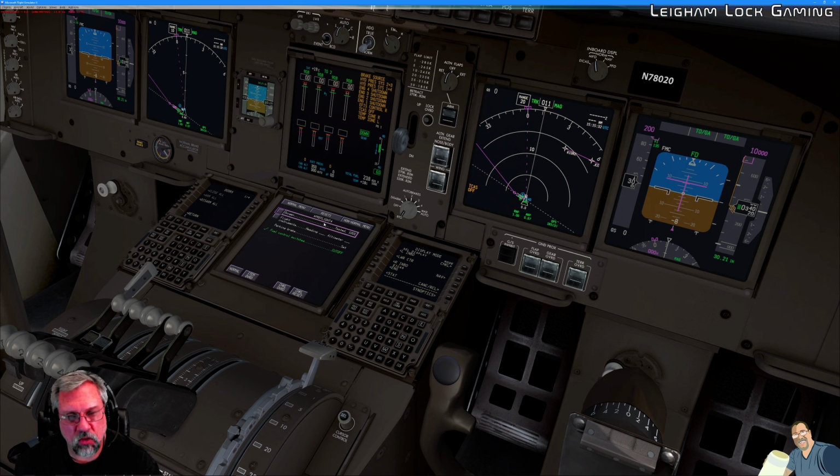They've changed the control mechanism so that if I click on this screen, the only thing that it's going to impact is what's highlighted in purple. To really control this screen, you have these cursor controls on both the captain's and the first officer side. You can turn that dial and notice it'll move the purple highlight around the page, and then you could select it by clicking this button.